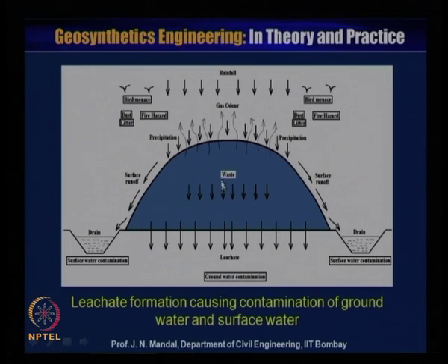And if in the waste material there is any formation of gas, then the gas will move to the air. Sometimes you can also see some birds appear at the landfill site. There is dust, and sometimes fire also happens in the landfill, which is also a fire hazard, and also there will be precipitation. So you need to control the formation of leachate, which happens due to contamination of the groundwater and the surface water.